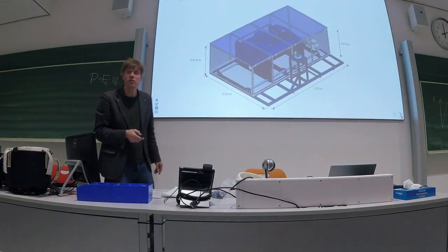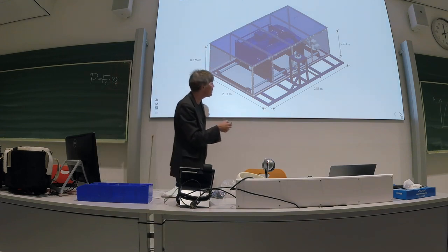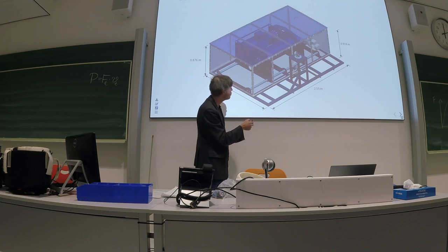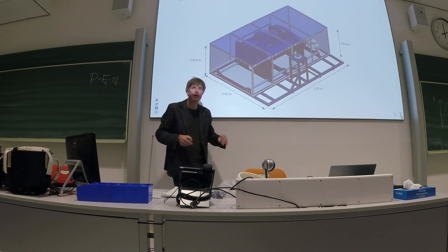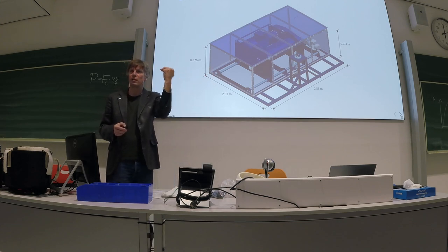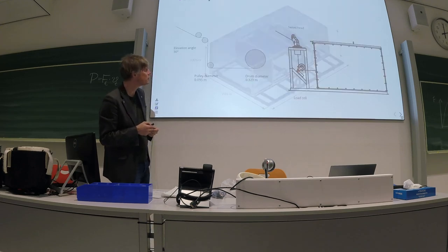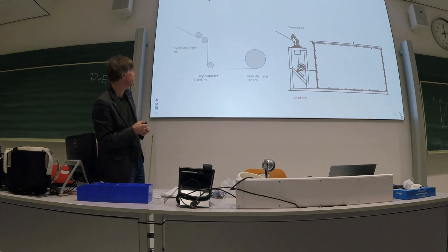That's the ground station. You see here the drum and the generator, and this is a belt drive to connect them. The tether comes from the drum, goes through 2 pulleys into the swivel head. The function of the swivel head is to be able to rotate with the wind. You see this illustrated here.